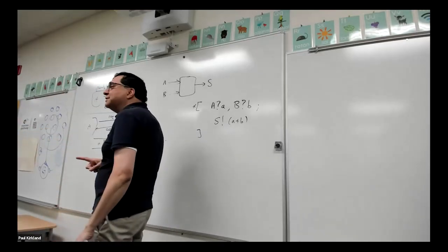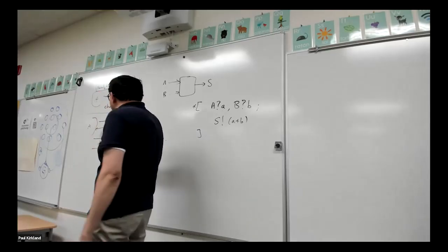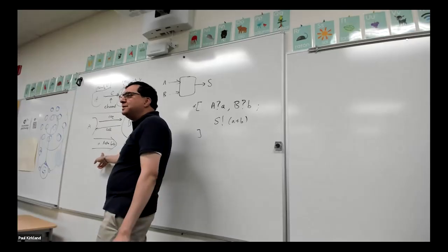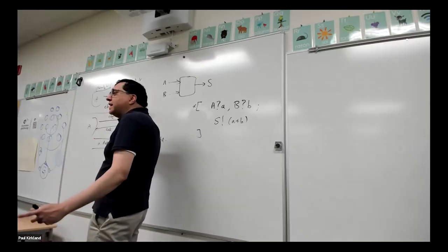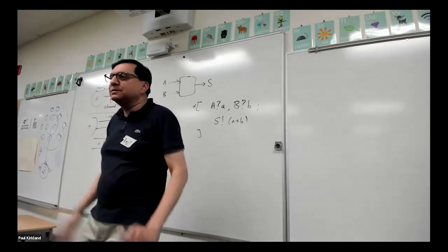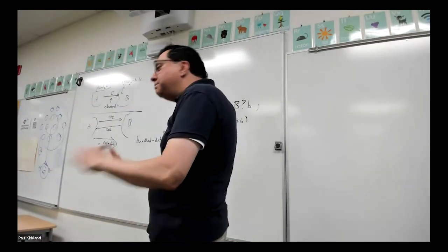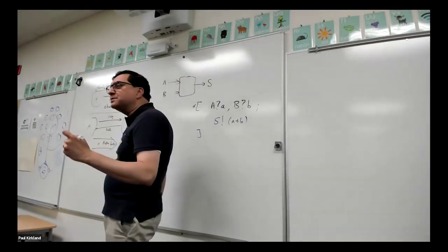This is not delay insensitive. This is not QDI, this is not even delay insensitive. This is a bundled data protocol, but it's the easiest one for people to think about. It is not a delay insensitive protocol because I could add delays here and break it. Now, if I wanted a delay insensitive protocol, the simplest version is I'm going to use 2N wires instead of N wires.